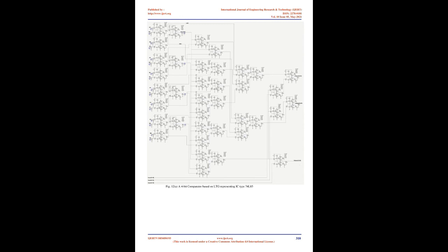With the help of the different logic gates we have implemented a 4-bit comparator, and by this single comparator unit we have been able to build an 8-bit or 4n-bit comparator. In single electron tunneling technology, we observe that the threshold logic gates are at least 3 times faster than CMOS-based logic gates. The operating temperature is kept very close to 0 K in real operation. At last we find that the implemented comparator provides a fan-out of the order of 10 to the power 9.